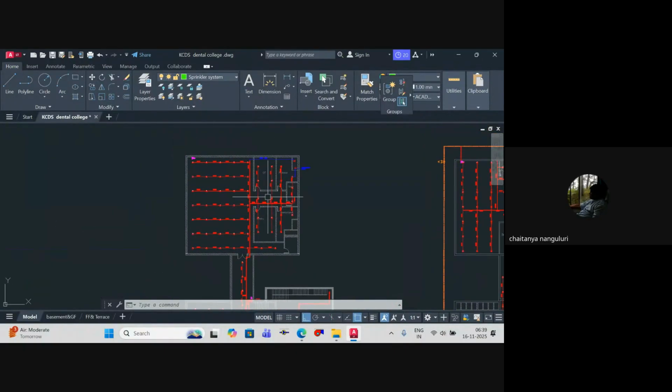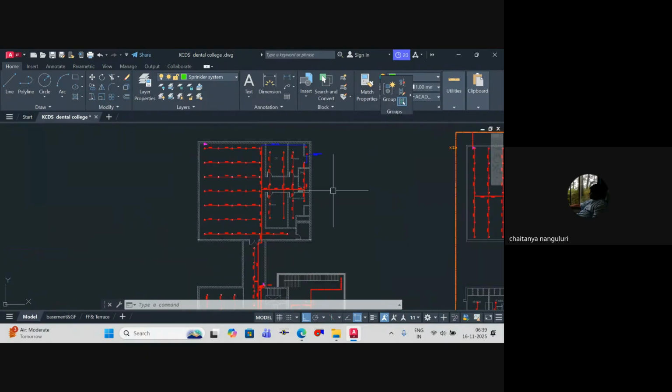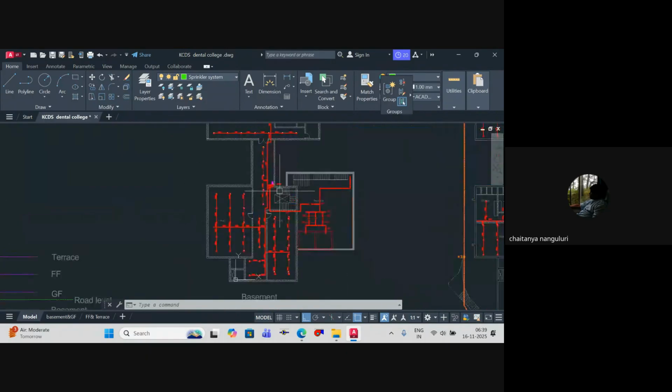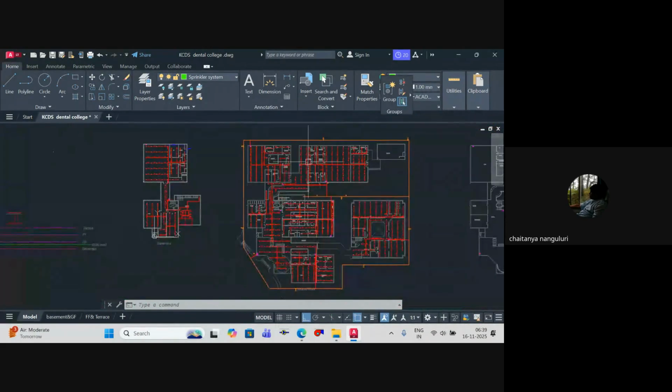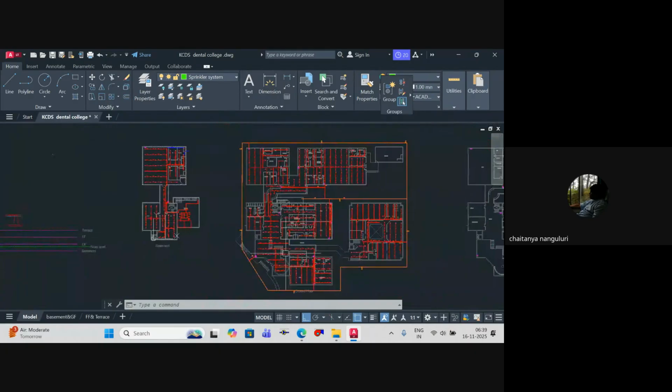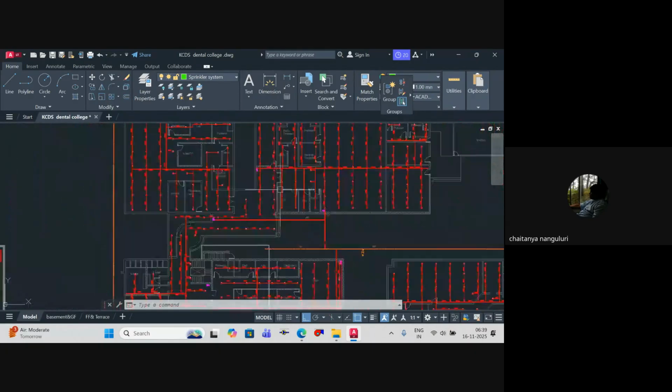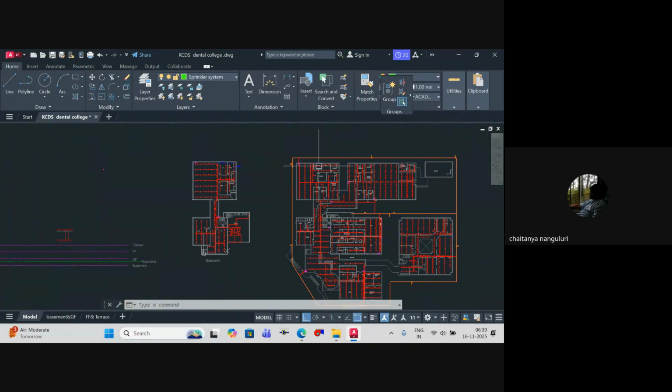So if you see this, you have a sprinkler system that is connected to a common valve over here. Similarly, whenever you've got a sprinkler system, you have to design it with multiple hydrants. As the area is quite big, I have taken multiple options. Now, what should we do? We have to connect our external hydrant to the sprinkler system.